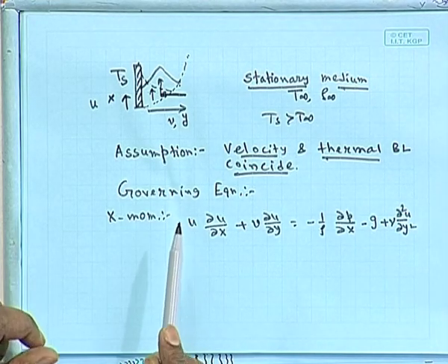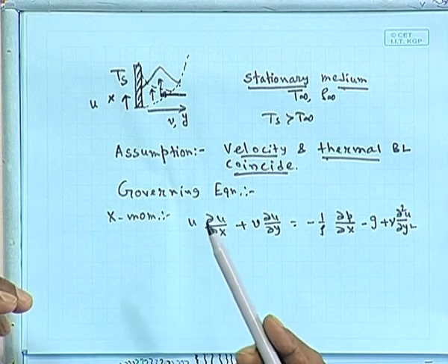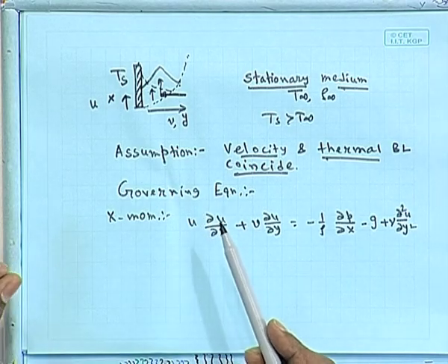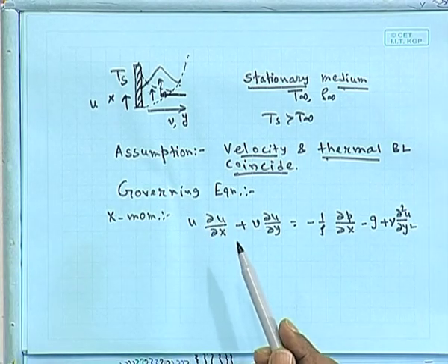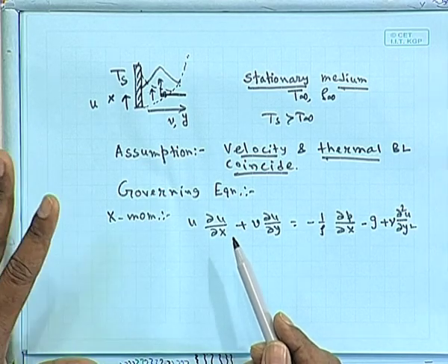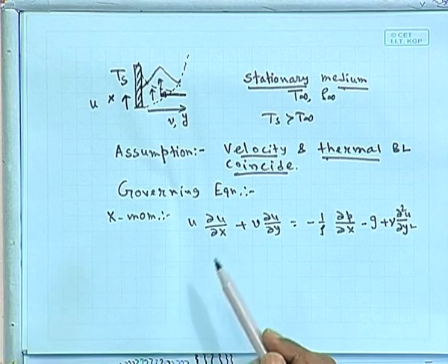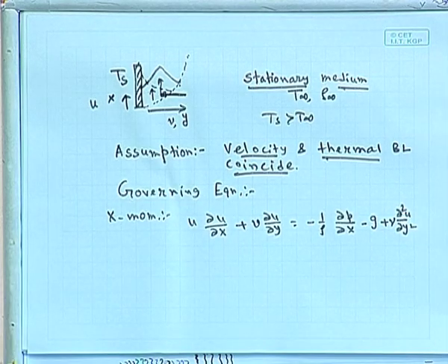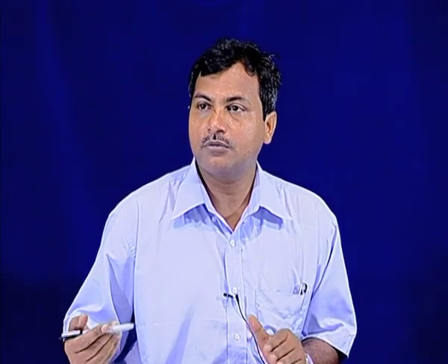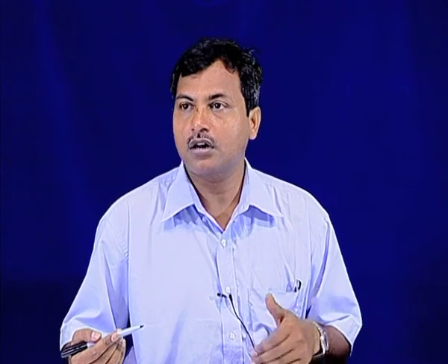Actually, in the definition of boundary layer as in forced convection, the fluid is flowing over a plate. The scenario here is not like that. In that case, there is simultaneous development of velocity boundary layer and thermal boundary layer at the same time, right? And depending on the Prandtl number and other fluid properties, the velocity boundary layer is either within or outside.